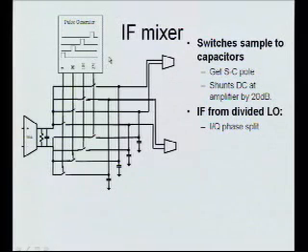And variants of this is maybe the most common way of generating quadrature in an LO these days. Usually, if you're trying to do what I'm doing here with image rejection, you would have an 1800 megahertz oscillator, divide it by 2, and use the divide by 2 to have 0 and 90 degrees, right? So a quarter of the way through, something changes and you divide by 2, and you grab that phase off. Do you want me to draw that?